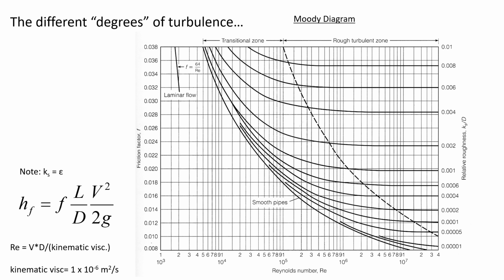Like if water is flowing from location 1 to location 2, so water is flowing downstream from 1 to 2. If this is horizontal, the pressure is going to be less at location 2 because the water wouldn't be flowing unless there was some reason for it to. So water flows either downhill, or in a horizontal conduit, water flows from high pressure to low pressure.